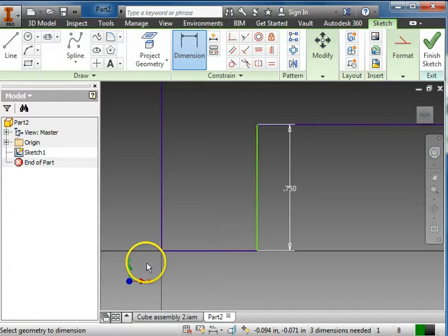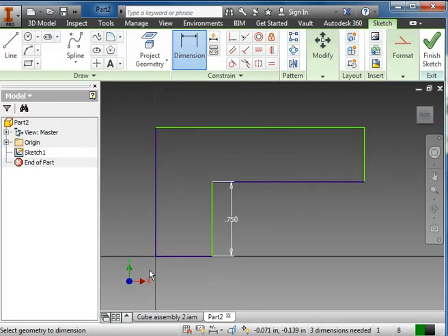When I click that, it enlarges. Now I want to say this is the root number that all of the dimensions that I use are going to be based off of. We call this parametric dimensioning. We're telling the computer to set up a database, and instead of saying the number that this measurement is, which we know is 2 times 0.75, which is 1.5, the distance from there to there is going to be 1.5.